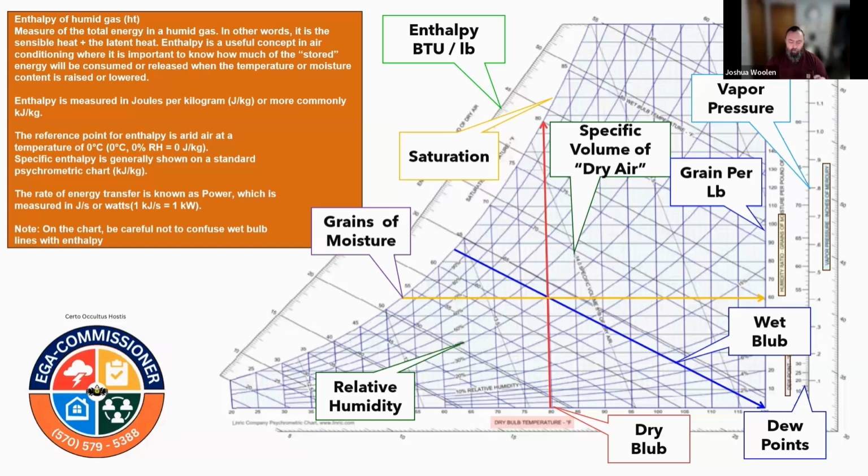They feel that once they've got the air to a certain temperature and to a certain RH, they are dry. Is that actually what we're paid to do? I ask you that because it's not what you're paid to do. It is assuming that this is the effective way to evaporate the moisture, when in fact we need to go to the vapor pressure and address the moisture within the materials, right?